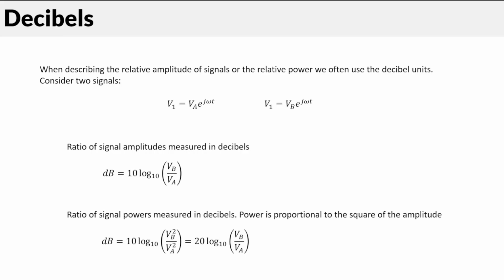I just want to talk quickly about the decibel, introduce the decibel to you. The idea is that the decibel is a method of comparing two signals. It can compare the amplitudes of signals. It can also compare the power contained in the signals. Now, decibels are used not just in electronics; they're also used in radio waves. They're used in sound, of course. There, you're usually comparing the amplitude of a sound to the lowest possible amplitude of sound that a human could hear.